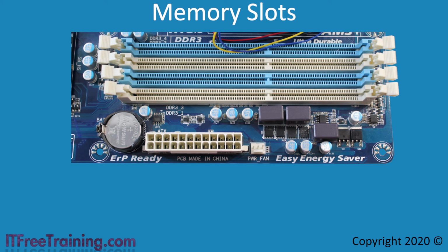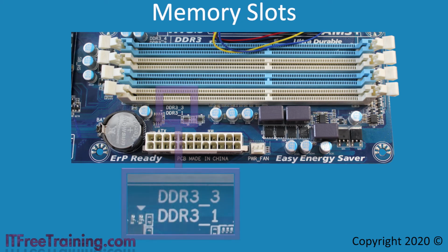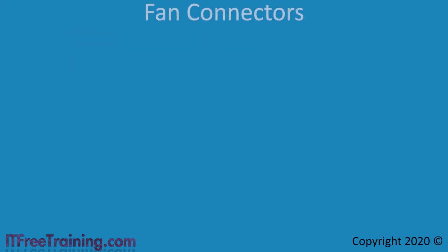You will find that memory slots are next to the CPU. Each slot is given a number, usually printed on the motherboard. When installing memory, it is important to ensure it is installed in the right slot. Some motherboards will not work unless a particular memory slot has memory in it, usually slot 1. In some cases, the slots may be color-coded. Generally, placing memory in the same color slots will allow it to be used together, giving a performance increase.